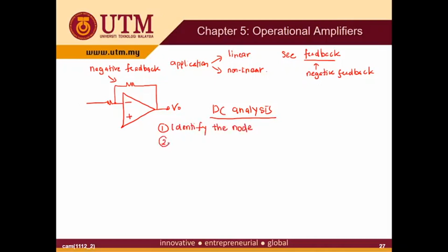And then the second one, you write down the KCL. The DC analysis of an op-amp circuit, most of the time, uses the KCL equation.